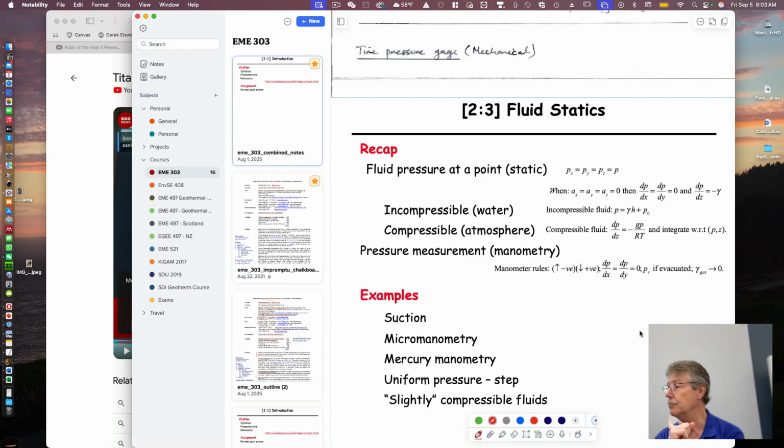We're interested in pressures because when you pump gas and the gas gets to the top of the tank, it stops automatically. The nozzle just decouples. That's because it's measuring pressure. You meter gas to buy gallons and gallons, and that metering is often done by measuring pressures in a Venturi tube, a tube that constricts in diameter. The pressure goes down when it constricts because the velocity goes up, and you measure that pressure differential to measure flow rates.